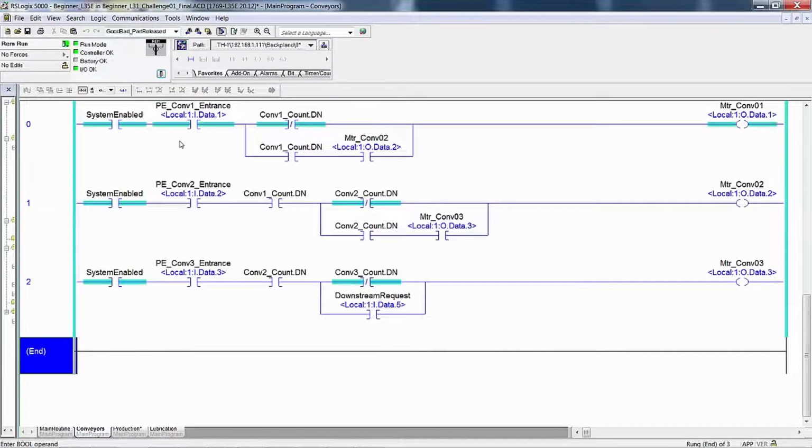There's PE1, flip it on, leave it on. Okay, the conveyor's running. Now we can leave it in this state because we really don't know how long the conveyor is or how long the carton is. Theoretically, if this carton was a foot long and the conveyor is traveling at 1 inch a minute, it's going to take 12 minutes to get the carton on the conveyor.